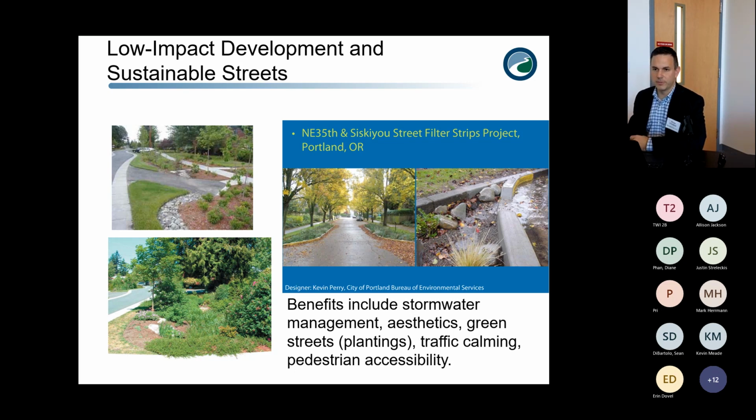And the other reason I bring this up, from the standpoint of the MS4 permits, is that municipalities have street projects that come up every year, right, that have grants to fund repaving roadways. Maybe those are opportunities where we can incorporate green infrastructure within those projects so that we can improve stormwater management and address these MS4 permits through other activities that the municipality is working on.